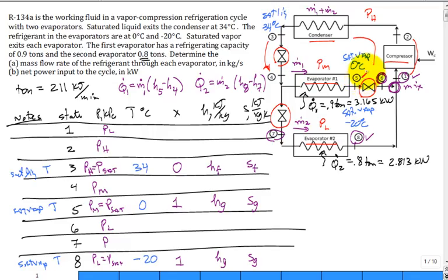So we know that the pressure and the enthalpy fix state 4. So this enthalpy at 4 is equal to the enthalpy at 3. You just bring that down. It's isenthalpic flow through that expansion valve. And the intermediate pressure, so we would go and we would get the temperature, and the temperature, from your experience, what do you think the temperature is at 4?